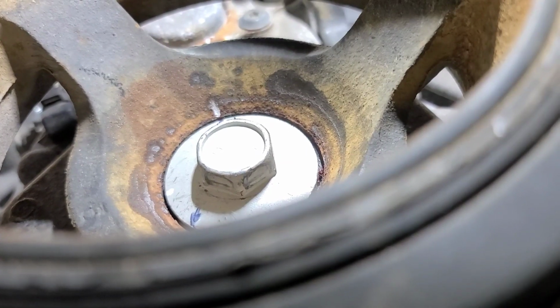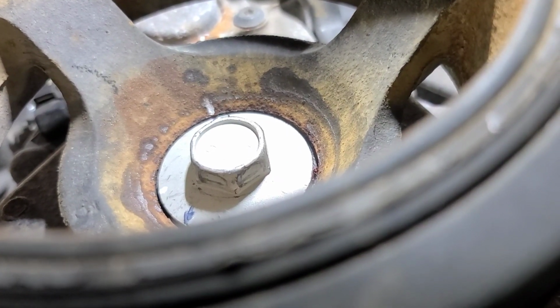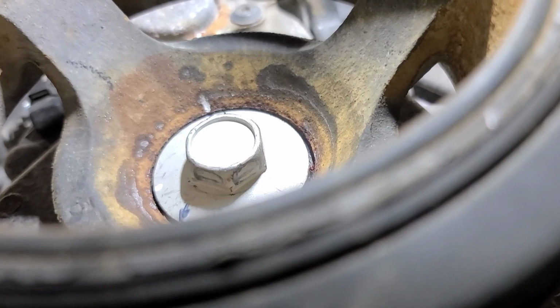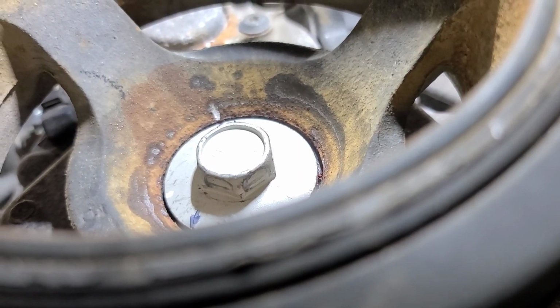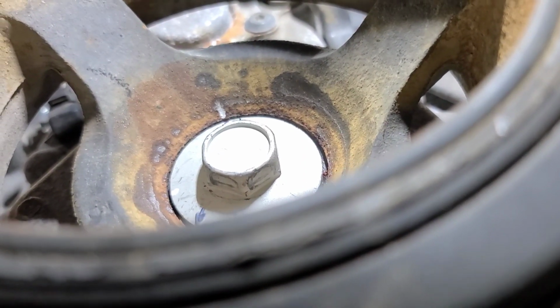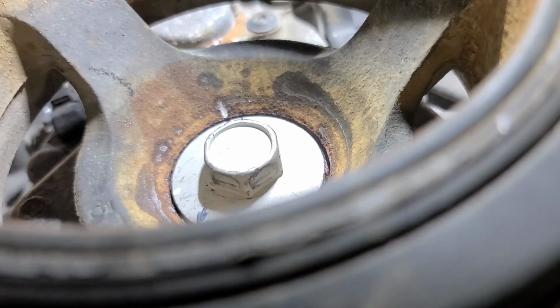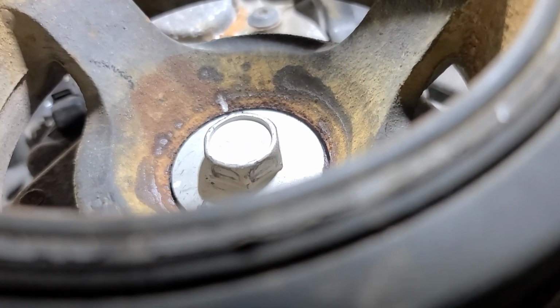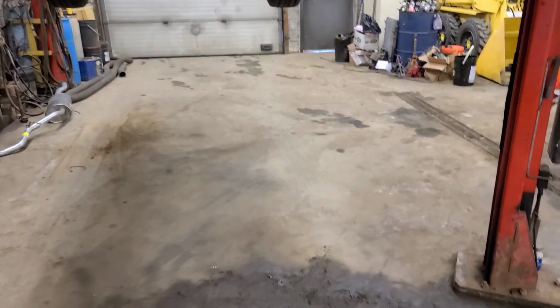And a black mark where 123 degrees is. So basically I'm going to rotate that until the mark at the 7 o'clock, 8 o'clock position lines up with the white paint dot. And it takes about 250-300 foot-pounds to turn it, so you need a 4-foot bar.